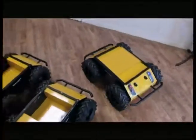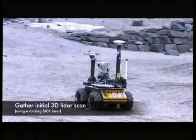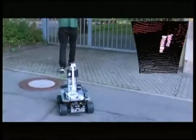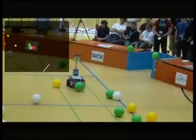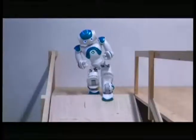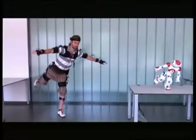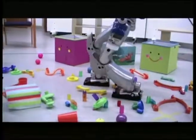So oftentimes what's happening on these platforms is there is a real-time layer operating beneath ROS. Like they discussed on the Nao, there's an RTOS and a different processor that's running, but ROS can sit on top and help with the perceptual systems that are quite general and applicable to many different robots. So some of these kinematics are wildly different, like that platform. There's a Nao with a laser on its head. And then this was doing more footstep planning. Again, ROS isn't running on the Nao, it's sitting on top and being bridged to it using the layer they described.